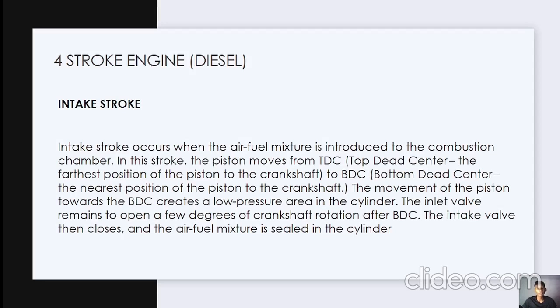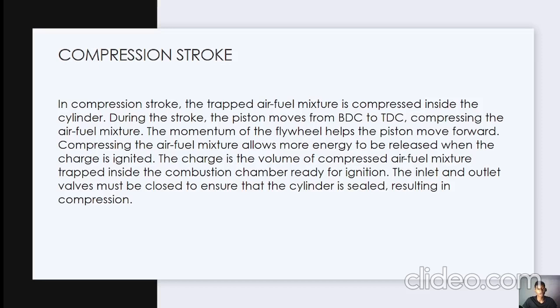The inlet valve remains open a few degrees of crankshaft rotation after bottom dead center. The intake valve then closes and the air fuel mixture is sealed in the cylinder. Next stroke is compression stroke.